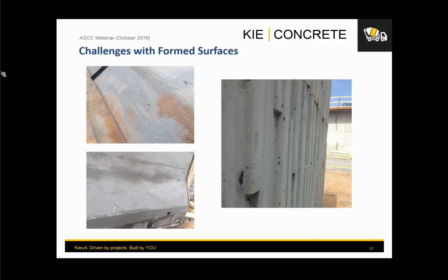The main thing with the form surfaces is understanding well what the different challenges are associated with different forms, and what the requirements by the owner are too, right? In some cases you have architectural finishes, and they may require surfaces without voids and without any surface imperfection, with a very minimum amount of voids.